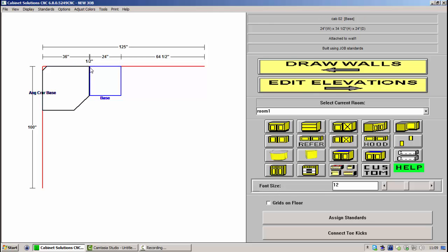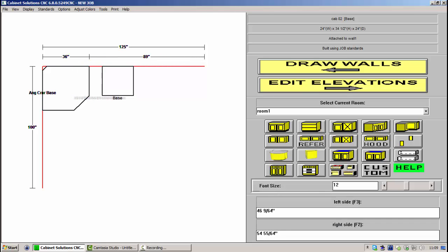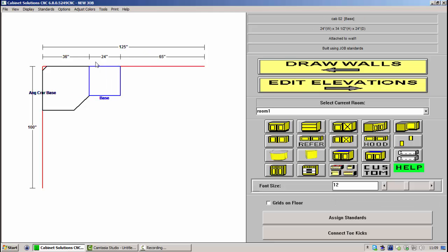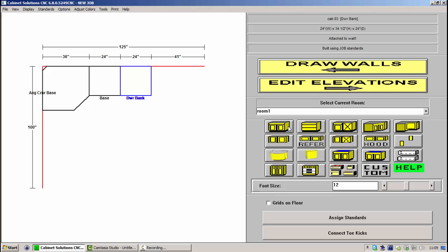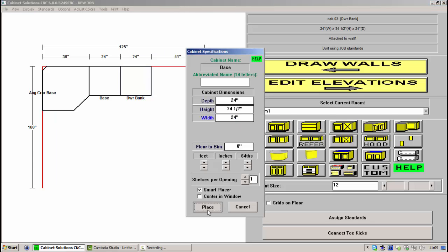That means this cabinet wall can potentially be marked as exposed, making it a finished end. So what I'm going to do is right click on the cabinet and then left click on the cabinet so I can move it back around. Overlap my cabinets and then click. And the program is going to snap them apart so that way they touch at that side. Let's go ahead and add in some more cabinets here. And let's do another regular base cabinet.